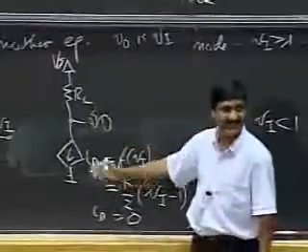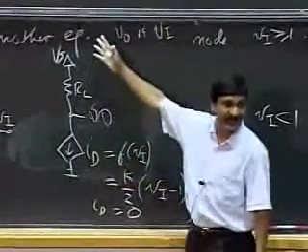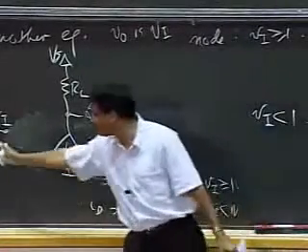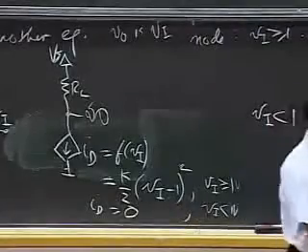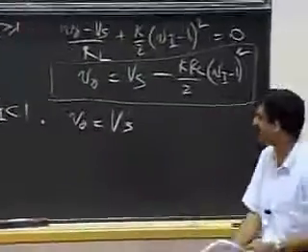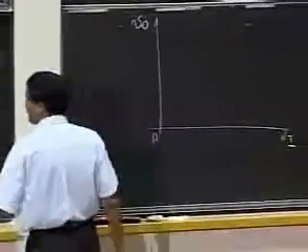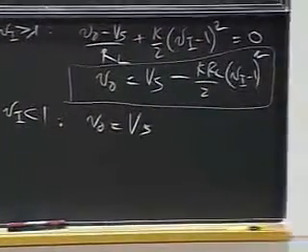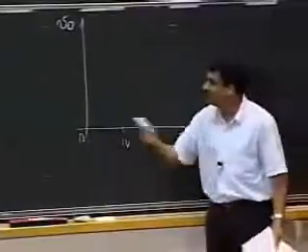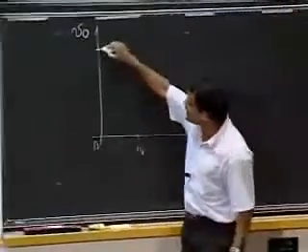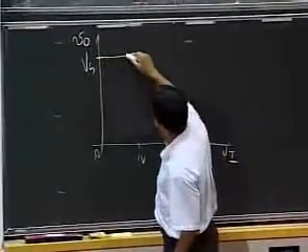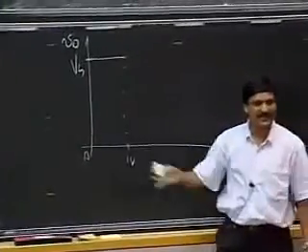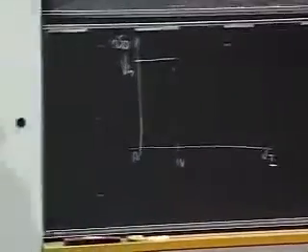This has got nothing. It's got an RL resistor connected to a supply and a dependent current source. I can apply some voltage Vi at the input. Very, very simple circuit. So let's see. As long as Vi is less than 1, the output stays at Vs. That makes intuitive sense, right?